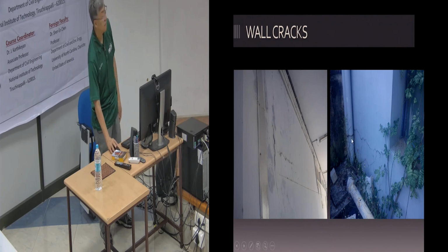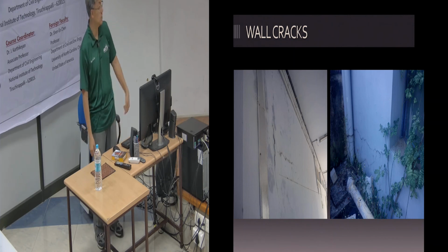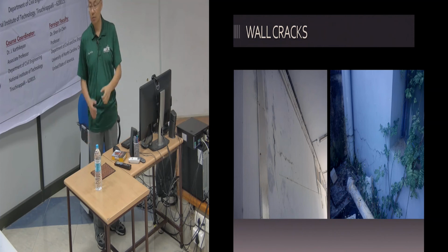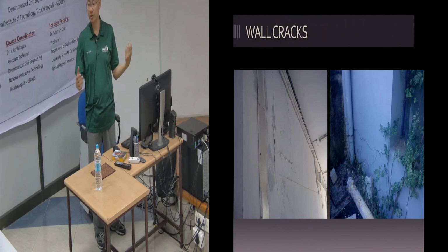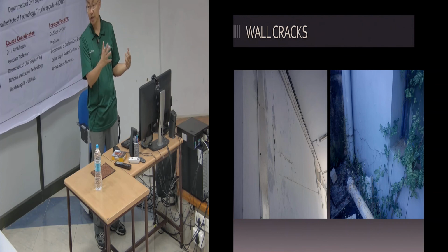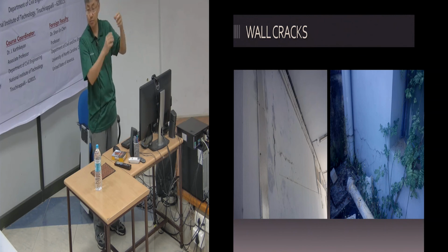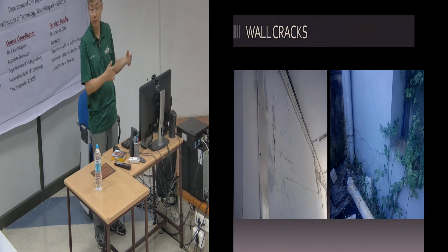Another thing that is very important is the attachments to a building, like pipes. Sometimes pipes are separated from the structure. Why? There is a reason. Those reasons are not necessarily structural, but it definitely indicates a certain problem. So don't ignore a separated pipe or a part of the window frame coming out.